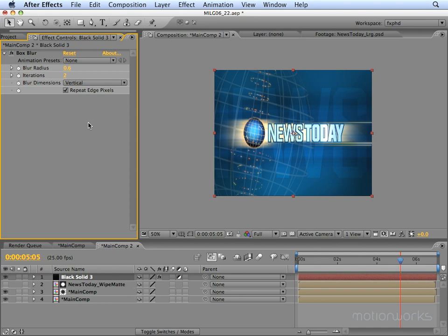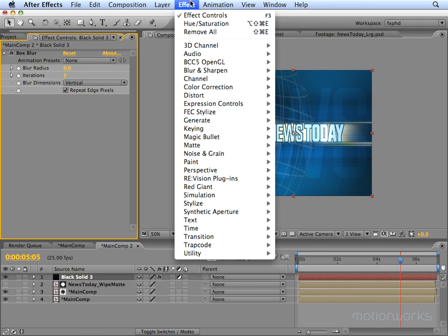So as I said before, really you should check it on a vector scope to check for your broadcast safe colours. We actually have a way of doing that within After Effects using a software vector scope, and the way that you do that is you use what's called Colour Finesse. Now you may or may not have this installed. I believe in some of the earlier versions of After Effects this comes as a separate CD, but you can check this in the effects menu, and if we scroll down to Synthetic Aperture you can see that we have